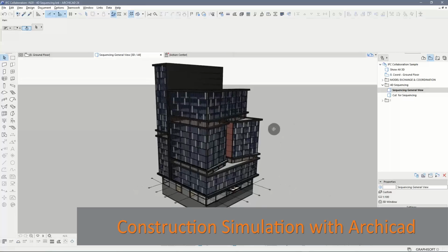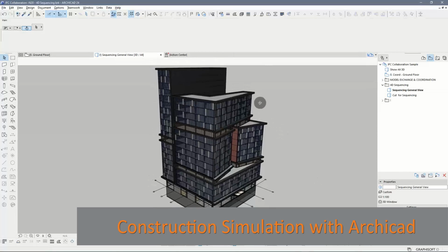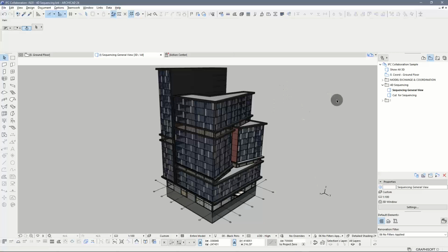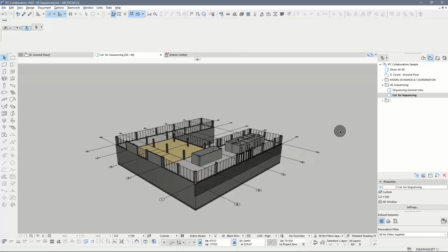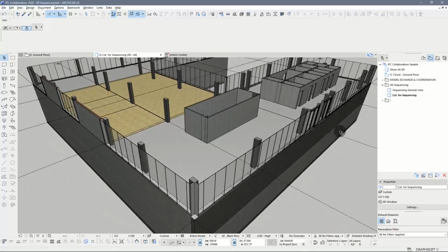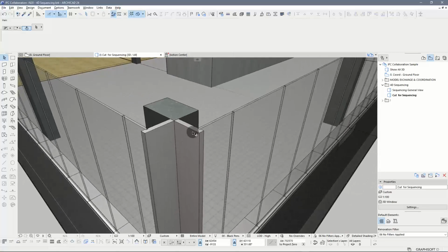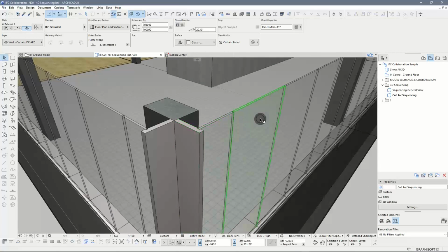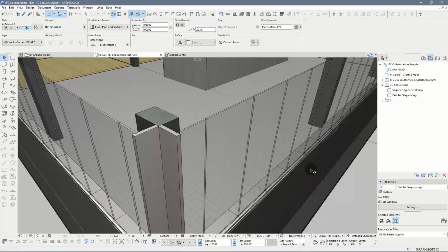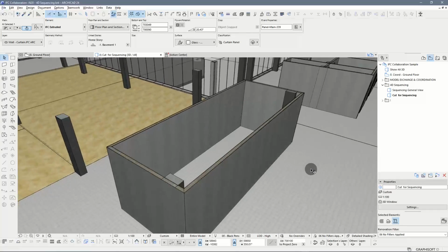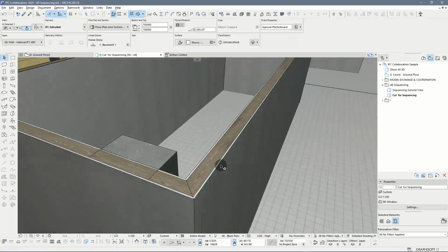Okay, back to what we were doing. So what I've done in here is I've got those Ifc models back into Archicad, not using my own working model. I'm actually using the same Ifc for the purpose of being able to use those sub-elements that I can't really manipulate if I'm just using my Archicad file. So let's go to a similar view. What I have in here is the same model, same everything, but this time, if I take a closer look, it's actually split into its individual parts. So now, because of that, I can manipulate what happens and I can build schedules on those.